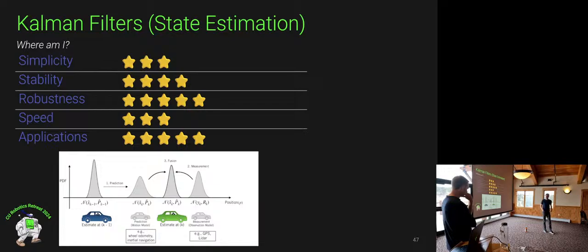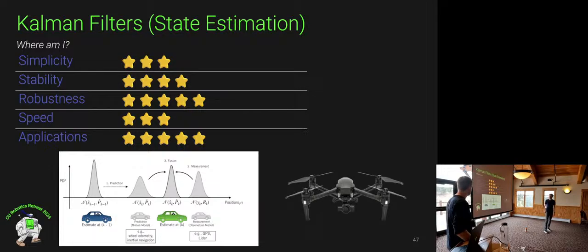The way a Kalman filter works is you have sensor measurements on your robot, and then you have where the robot thinks it is. As the robot does stuff in real life, those things diverge. The sensors might think you're in a different location than where the robot thinks it is based on what inputs it's been given. The Kalman filter reconciles this information and provides you with a more accurate state estimation. That's what this drawing is showing. This is very ubiquitous. It's used in all kinds of different robots for having a more accurate estimation of your state.